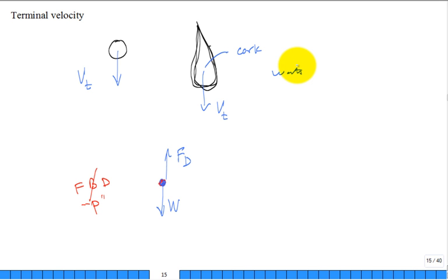It's not even going to sink. What's it going to do? Float. Buoyancy. So we could have another one, buoyancy. So those three typically you need to account for. So you have the buoyancy, the drag, and the weight. And when they sum to equal to 0, that'll give you the terminal velocity.